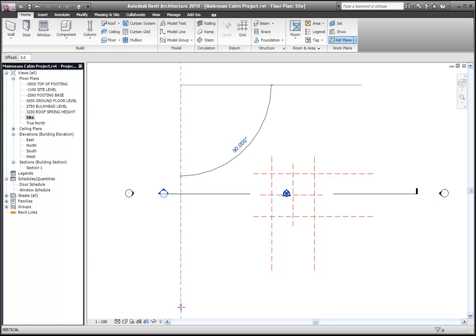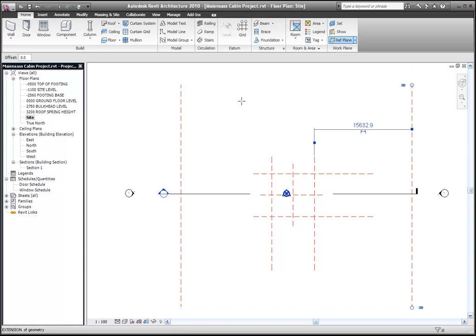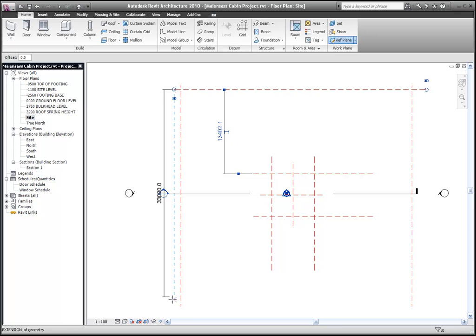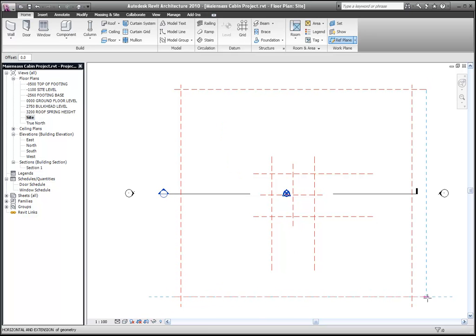It doesn't place in a straight line, so you probably need to create some points for it to attach to. So that's what we're doing. I'm placing 4 reference planes in my side view. The reason I've gone to side view is because the topo surface object itself is turned on in this view, not in the plan views, not in the ground floor plan view.